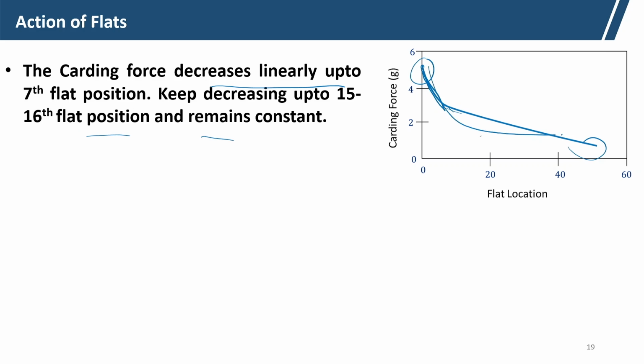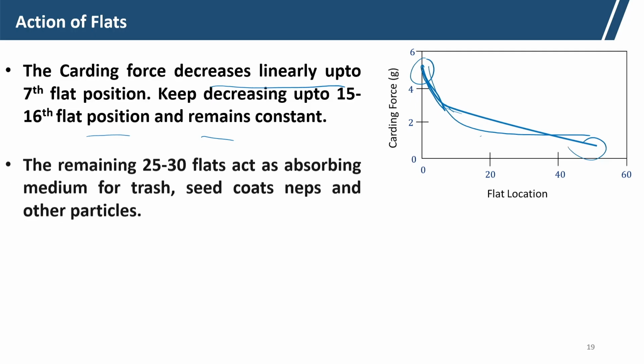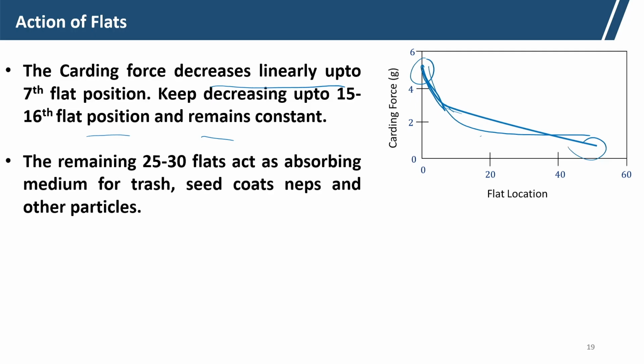Typically it is like this. The remaining 25 to 30 flats are absorbing minimum trash, seed coats and neps, because within the 16th flat the main function is completed.